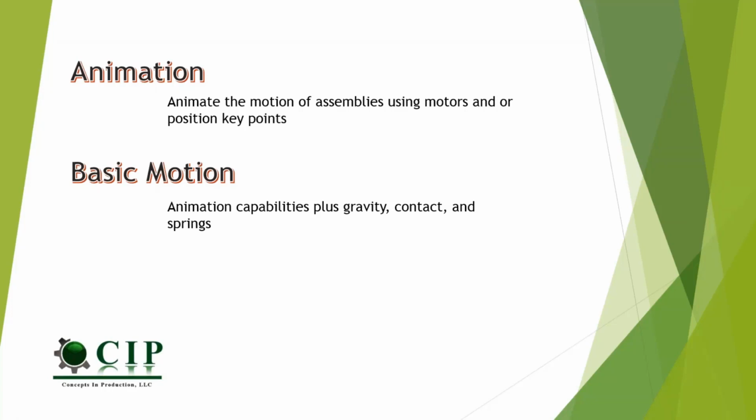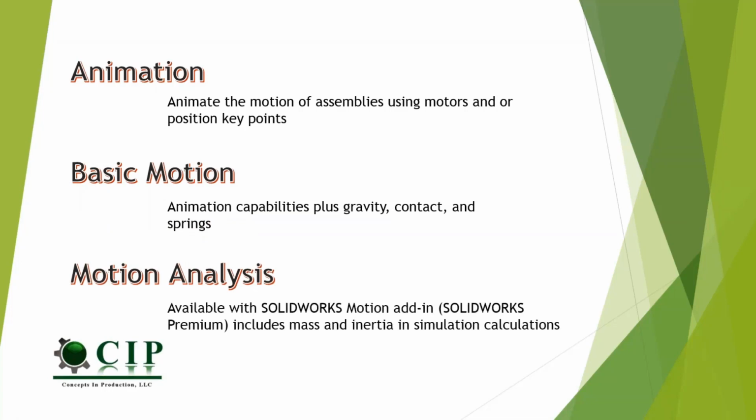And then the last little module that SolidWorks Motion Study gives you is motion analysis. Motion analysis builds on what animation and basic motion already gives you, and it enables you to include mass and inertia in your simulation calculations. And this is available with the SolidWorks Motion add-in, and that comes with SolidWorks Premium.